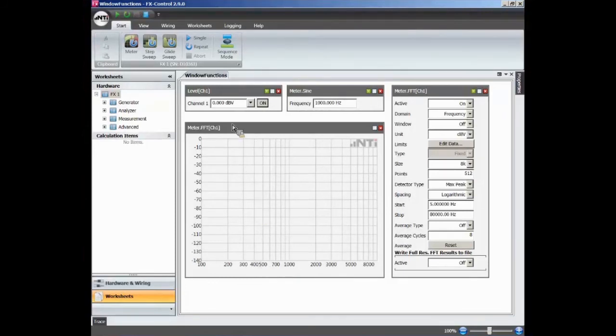And I have here a sine wave with 1 kHz frequency without windowing. Let us take a look at this spectrum. It would look like that. And this is a typical smearing or leakage effect that you see here. The 1 kHz, you would expect a nice pure singular bin here, but in fact, due to this leakage effect, you have this smeared spectrum in reality.